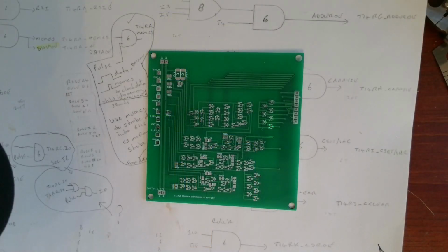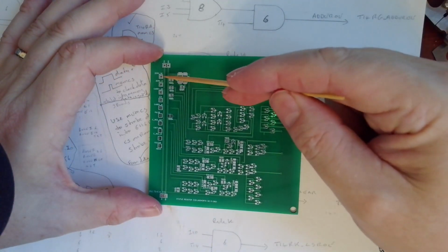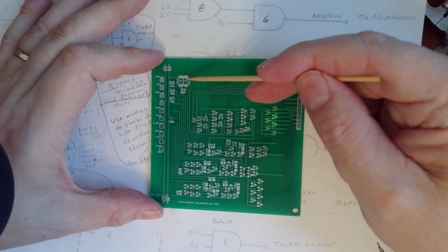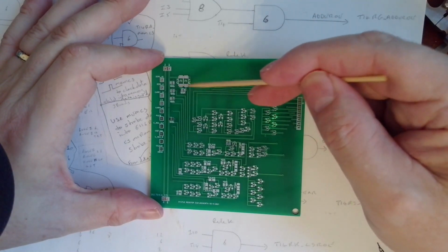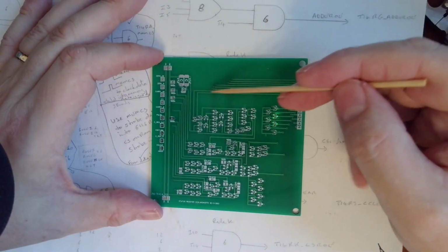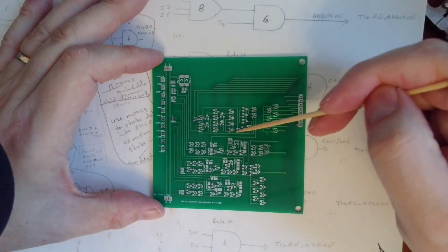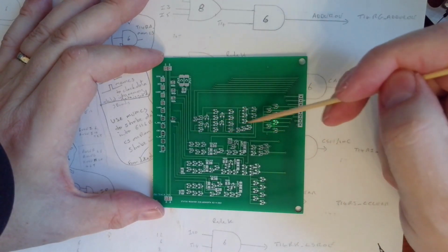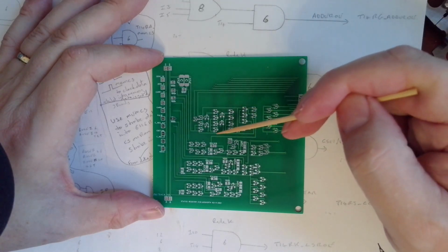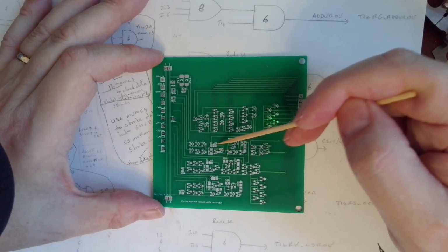Now this is the status register board. So we've got all the control signals coming on the left, quite a few on this board. Here we have the usual decoupling capacitors and the magic blue smoke resistor to limit the current to all the rest of it. So these here, all the NOR gates and AND gates for calculating the 0 flag, which gets fed back down here into the input to the 0 flag register.